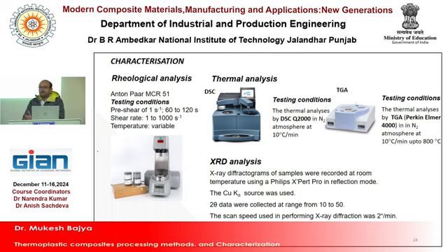And then XRD, generally you want to see what kind of crystallographic structures the materials have, and how these crystallographic structures change with the temperature, with the processing temperature, and how the orientation of the fibers is affected. Definitely whenever you are processing at a higher temperature, that will affect the reinforcement material as well as the matrix materials.